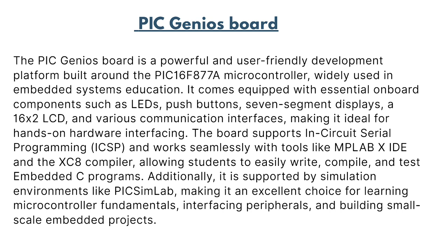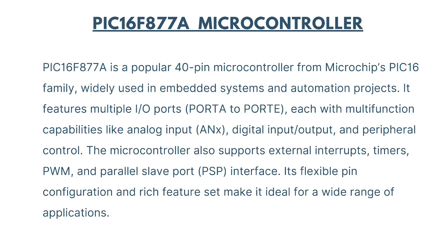The board supports in-circuit serial programming, that is ICSP, and works seamlessly with tools like MPLAB X IDE and the XC8 compiler, allowing students to easily write, compile, and test embedded C programs. Additionally, it is supported by simulation environments like PICsimLab, making it an excellent choice for learning microcontroller fundamentals, interfacing peripherals, and building small-scale embedded projects.